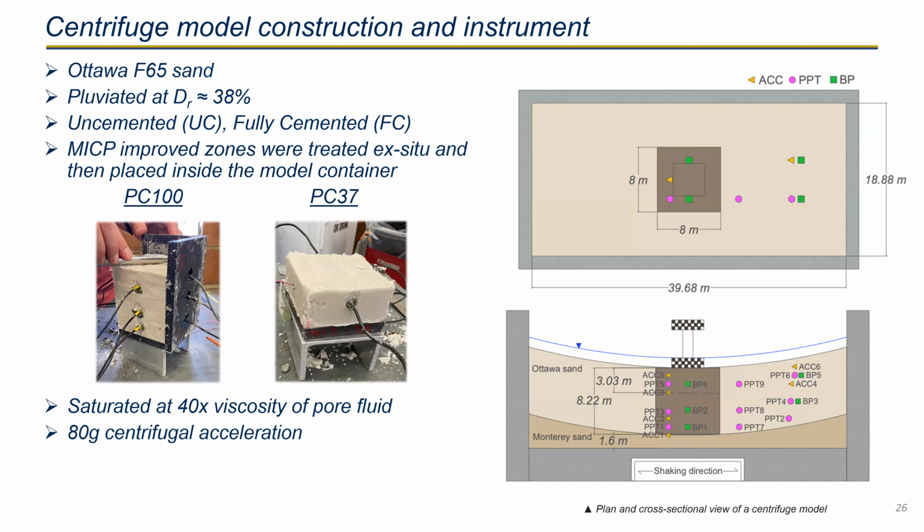But if you want to apply this technique to the field, then you need to get a core from the field and do some lab tests to find the optimum treatment condition. But definitely it will be affected by the natural soil properties as well. Thank you very much.